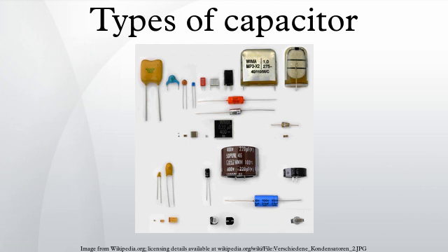The decoupling capacitor supplies transient current to the chip. Without decouplers, the IC demands current faster than the connection to the power supply can supply it, as parts of the circuit rapidly switch on and off.